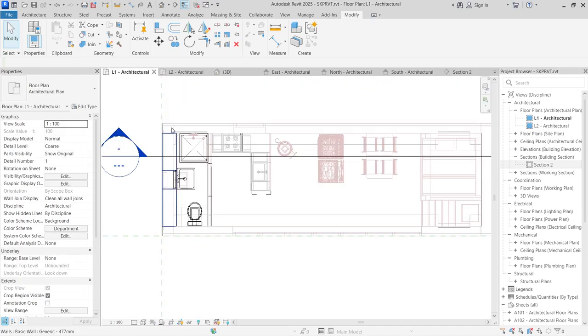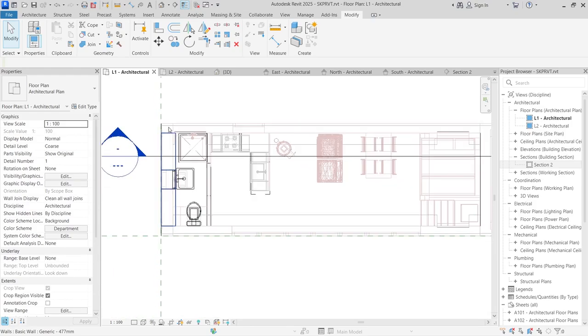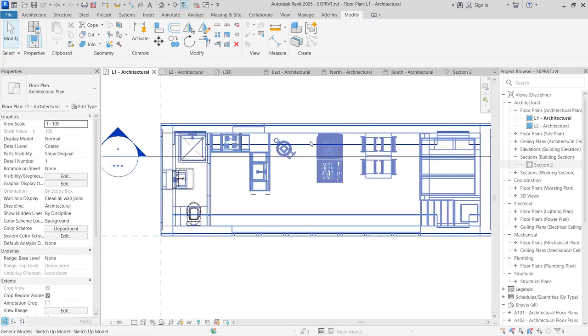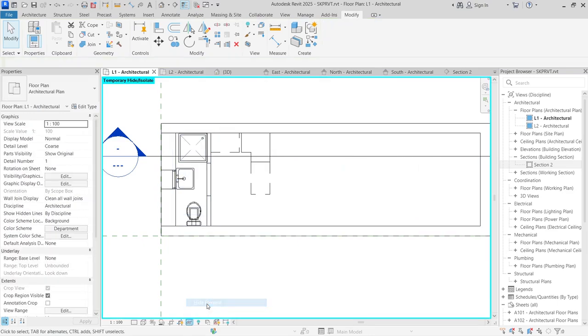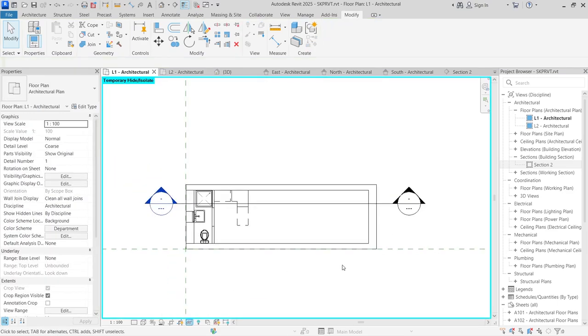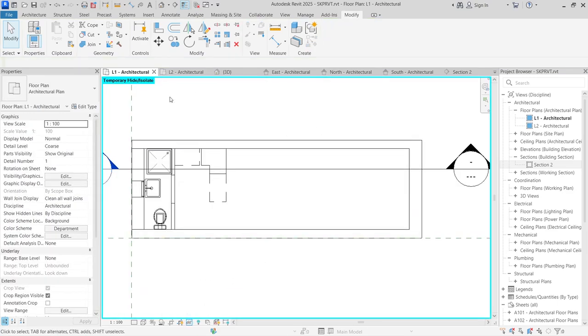So I'm going to select level 1 now, and select this generic SketchUp model that came in with us, and below here I'm going to hide that element. We can see where there's a pair of glasses. Just click those glasses and say hide element. Now that element is hidden, we have our pure Revit model, no SketchUp interference in between.